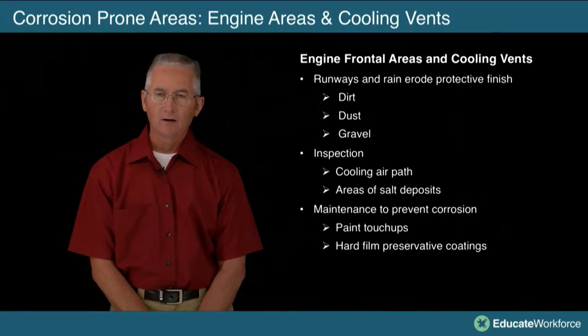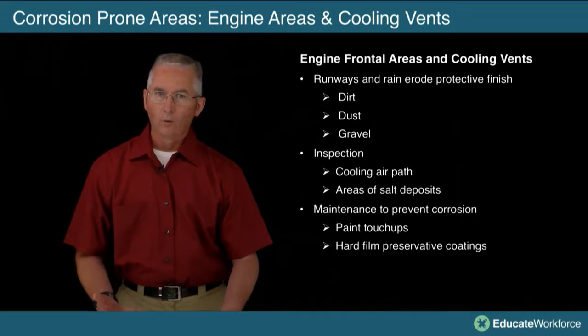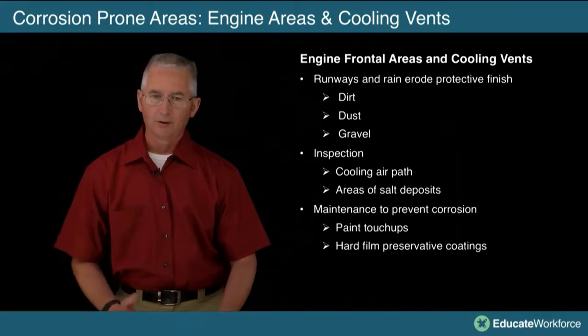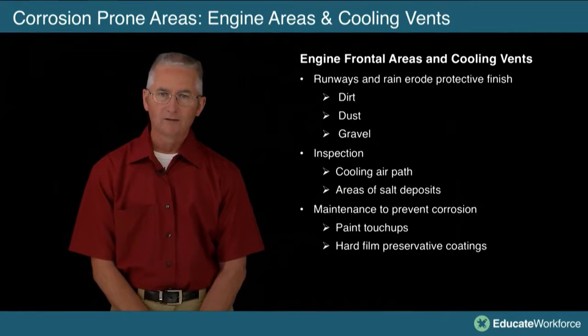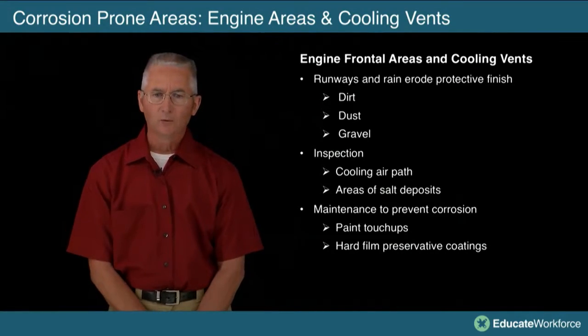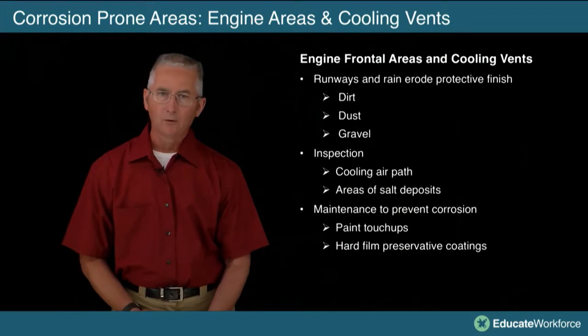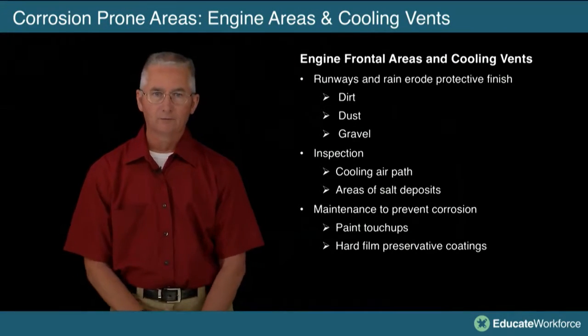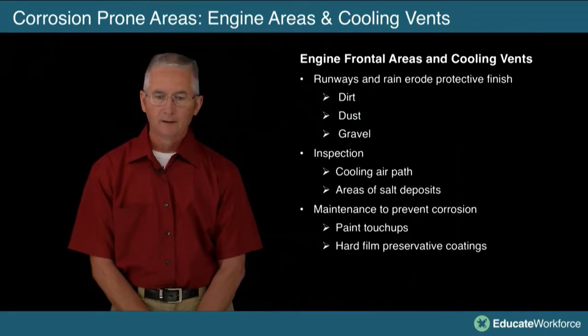Things just taking off, going down the runway, the sand and the debris from the runway, or the exhaust fumes from another airplane blowing on it. All of these things cause the dirt and the debris to blow against that intake and to wear the paint out. A good inspection, look for the cooling path. Look where the cooling air is flowing. Do you notice any paint peeling? Do you notice any bare aluminum?